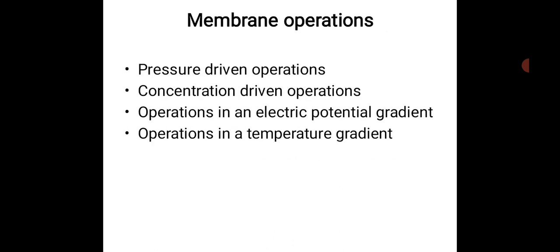The membrane separation process can be classified into pressure driven operations, which employ the pressure difference as the driving force. Then concentration driven operation is operated based on the concentration gradient. Then operation in an electric potential gradient, where the voltage difference is applied as a driving force. Then operation in a temperature gradient or temperature difference.